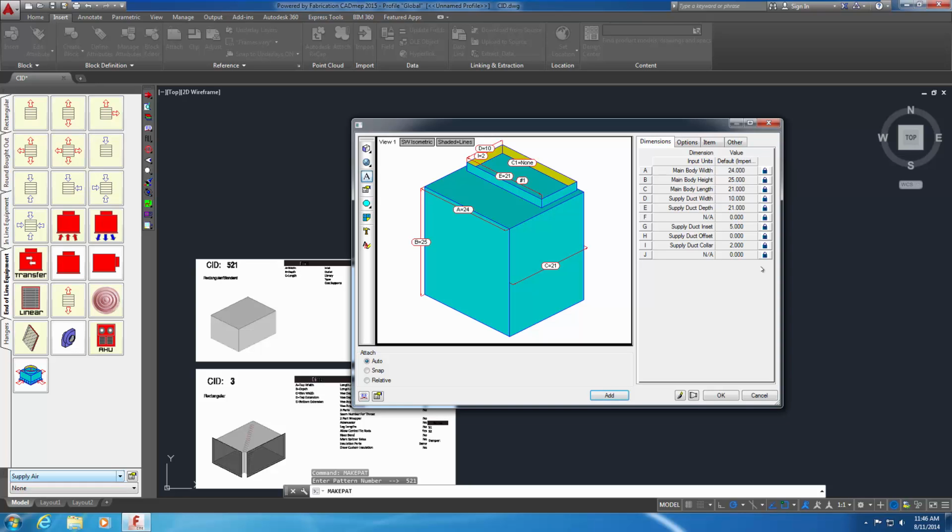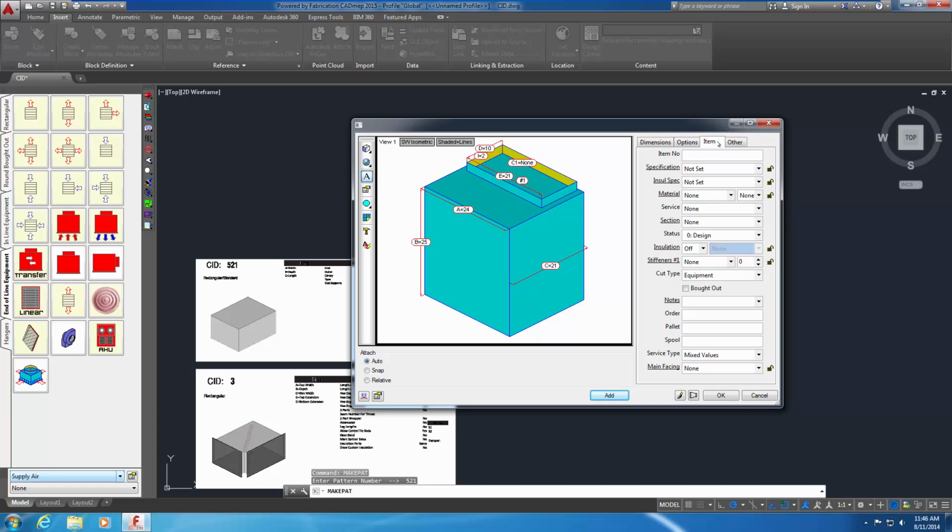Select the Options tab. Make no changes to the values. For this exercise, lock all the settings. Click the Item tab. You may enter and lock specific database settings for this item. Set the pressure class to Ductwork -2WG. When you set this value, the field is automatically locked. Enable the Bought Out option. Scroll down the list and set the service type to 39 AHU.